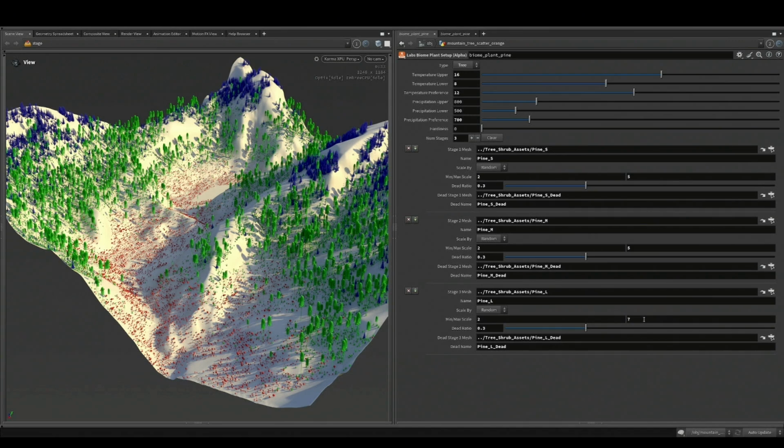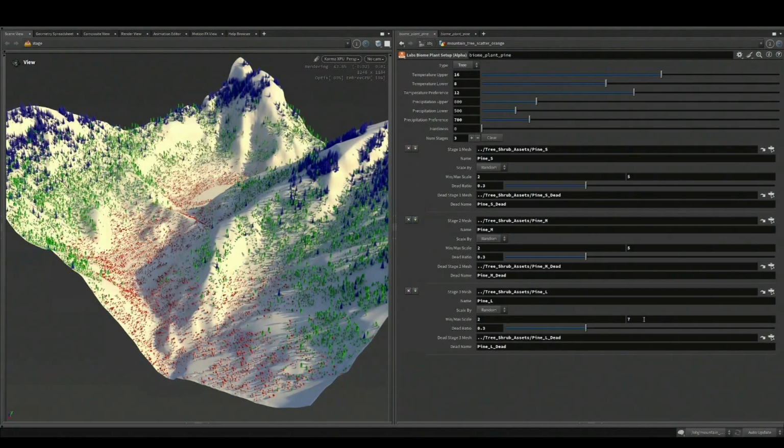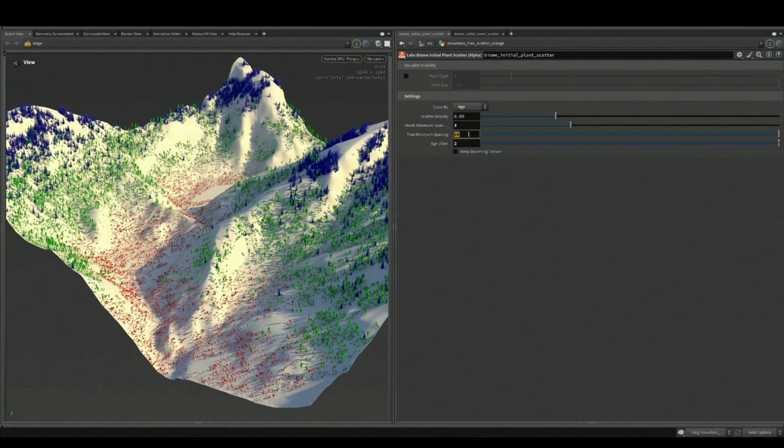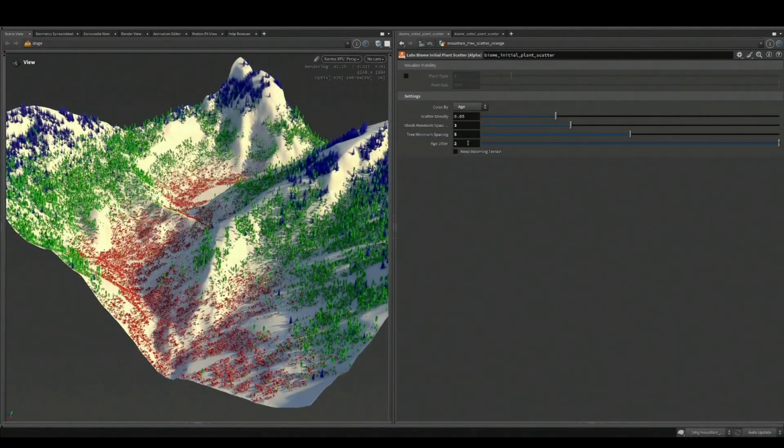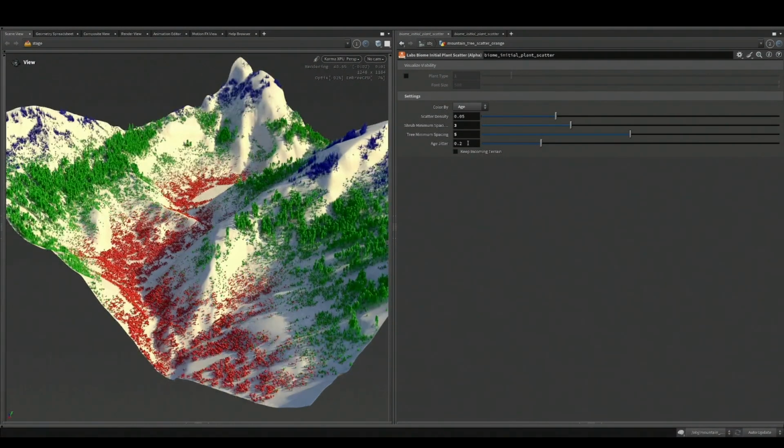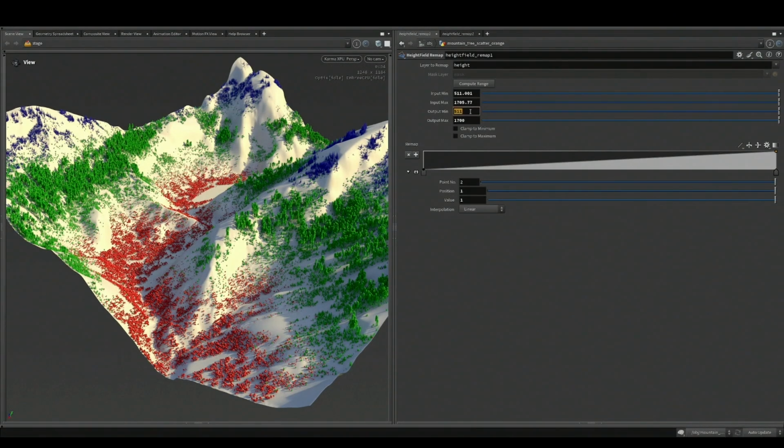For instance, you can change the size of the assets with some global control. You can change the spacing, like how close to each other they are. This is just the vertical slice parameters, so they're not super sophisticated just yet. And this is recorded in real time, playing at one-times speed. You could potentially evaluate your results in Solaris, so you can get this nice lighting while still playing with the SOP parameters. Because when some of the trees get too dense in the SOP context, it's very hard to see what is what.